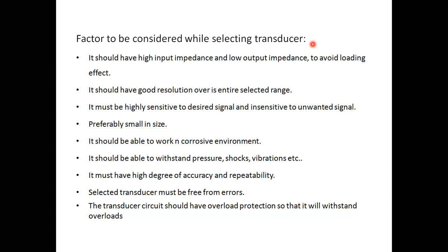So high sensitive and low sensitive, these two extremities I have to avoid. If sensitivity is high, stability decreases; if sensitivity is low, errors come. So I have to choose optimum sensitivity for the instrument. Okay,